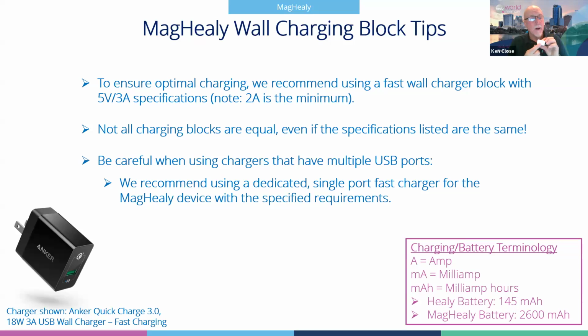They may list that much power on the label, but when they actually put a load to it, it's not the same. They have what's called peak or max output, and then what's called sustainable or typical. They'll always advertise the peak, by the way, to show you a bigger number, but what you're actually sustaining may be as much as 40% less than that number.